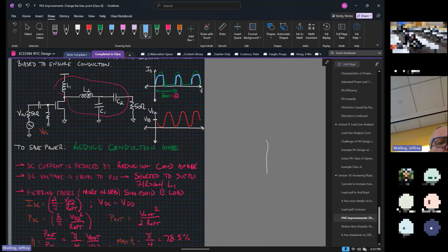Oh well, with respect to intermod, what we really have here is the GM of the device. We measure the gain of the device as GM times R, right? Now GM is defined as the change in drain current due to a change in input voltage. So no matter what happens here, my GM is going to be a much more nonlinear function than the Class A amplifier will be. Bear in mind, we might be talking about a Taylor series expansion, but really these are much more nonlinear circuits. So oftentimes we have to talk about a Volterra series expansion, which includes memory effects. We have big parasitic capacitances and inductors in the circuit that will cause the voltage and current to be held in memory for some period of time. So if I do that expansion, I'm almost always going to find that the Class B is worse. But that is hand wavy, I'll give you that.